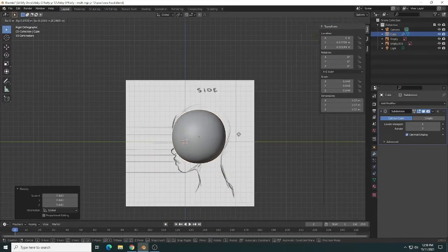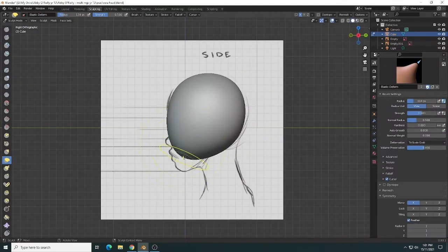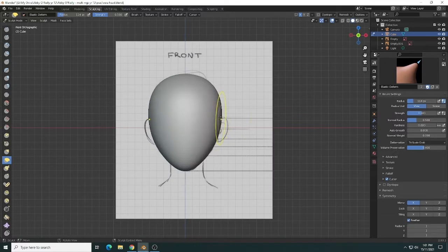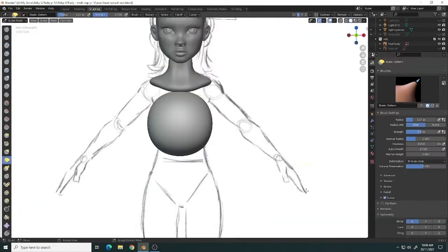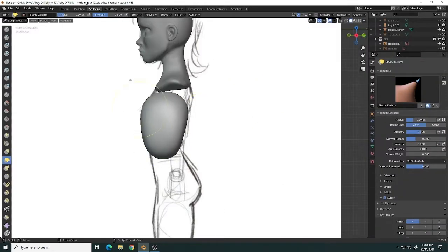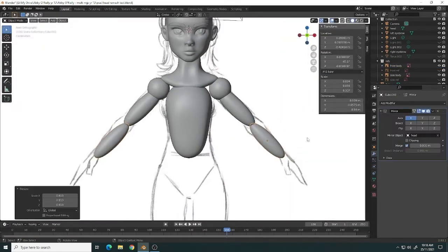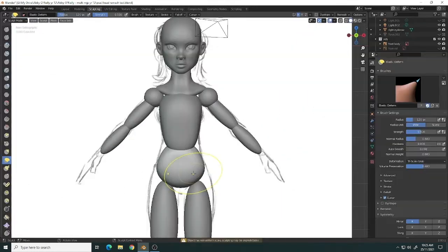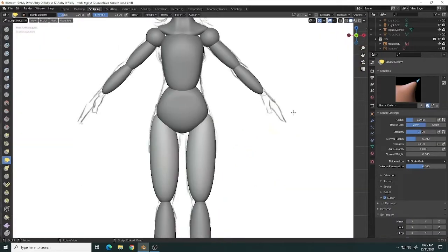From here, I began with the modeling of a 3D character as the central figure for the film. To achieve a more realistic and natural appearance, sculpting was the decided form of modeling. However, this required previously drawn references scaled to the correct size to assist with proportions. For all components of the head and body, I used a cube with high subdivisions for the base geometry to minimize the possible issues with triangles or n-gons. To maintain symmetry and efficiency, symmetry was turned on and mirror modifiers were used on all limbs.